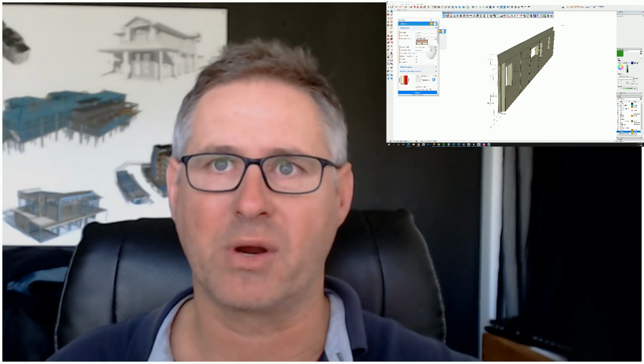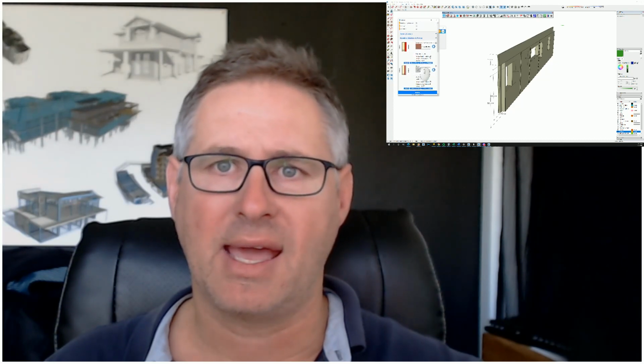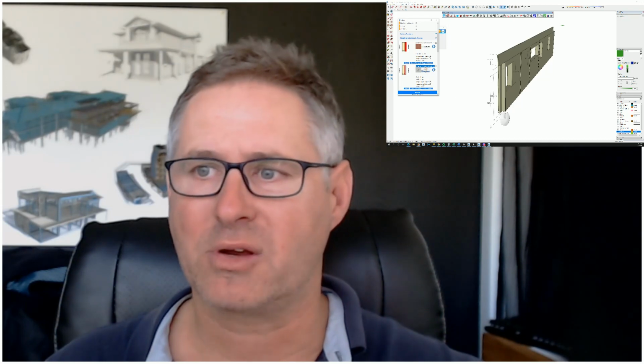Okay, so in this particular case, I've actually chosen a brick wall. I probably want to go a lightweight multi-skin wall, and then I can actually go through and choose a product on the outside. So the red here is signifying which product I'm choosing. And if I go in and choose, I'll choose, say, a Kingspan 2mm. I'm not going to worry about these measurement guys because I just want to get it done so you can see. But you can see that this Kingspan is 50mm wide.